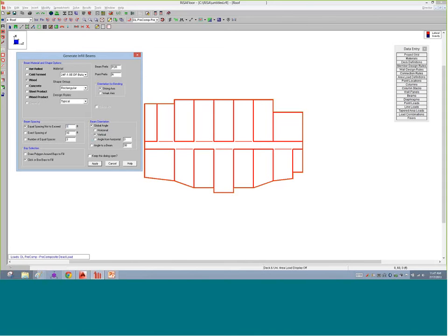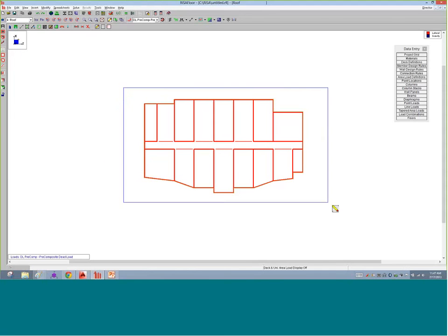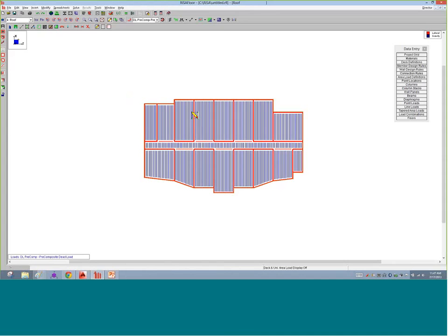Let's say these are going to be a little bit tighter spacing, and we're going to apply these in as vertical elements there. There we go. So we see that they all apply directly to our structure. What I want to do here is apply a slope to this. So I'm going to go ahead and use my slope tool to do that.